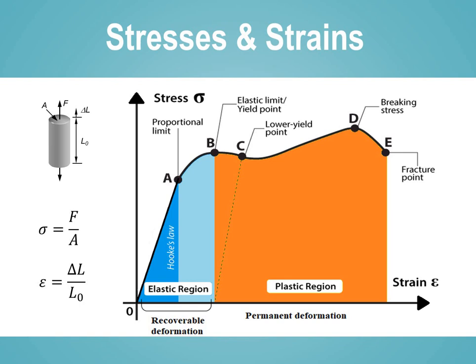To start, we have on the screen the relationship between the stresses and strain for a ductile steel. We have a cylindrical sample of steel that is being pulled by this force F that we increase, and we record the deformations. In this curve of stresses and strain, we can sketch, we will differentiate several areas or several regimes.